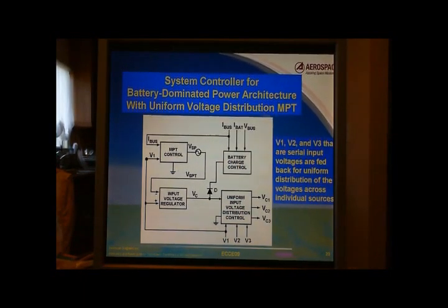As soon as the battery charge controller fails to regulate its charging current IBAT to the target, or fails to accommodate the Vbus or battery voltage to the target, it will cause the diode D to reverse bias. That removes this part from engaging the voltage VC.